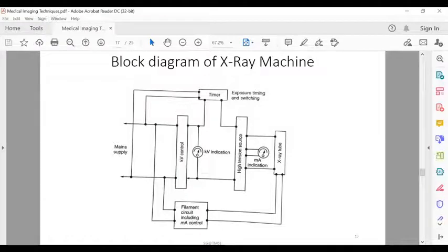So at room temperature between 18 degrees centigrade and 25 degrees centigrade, the working solution will maintain its properties in an open tray for just 4 hours, and the stock solution kept in a stoppered bottle will preserve its properties for 2 months if the bottle is half full, and up to 6 months if the bottle is full. Now, these shelf life figures can be improved by keeping the solutions in the refrigerator and are reduced at high temperature.